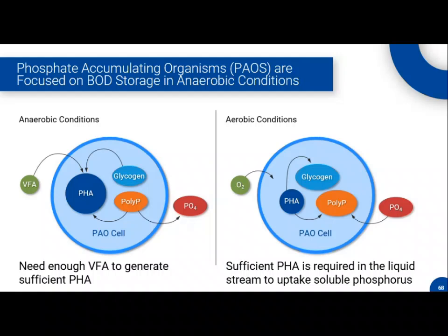So it's not so much that the anaerobic condition is something special that like the PAOs just really need to be swimming around under anaerobic. The important piece of it, the reason that anaerobic condition is important is because it means there's no oxygen and no nitrate, because our PAOs can't compete for the carbon with normal heterotrophs if there's either of those two things around. Right? So the anaerobic conditions are the indicator that you created the conditions where only the PAOs can go after the VFA. That's what the anaerobic conditions mean.